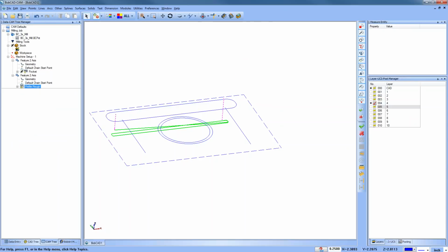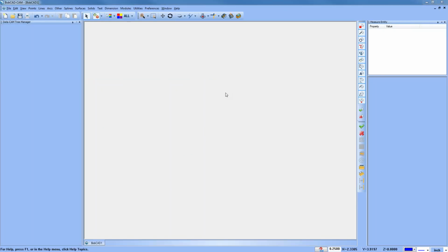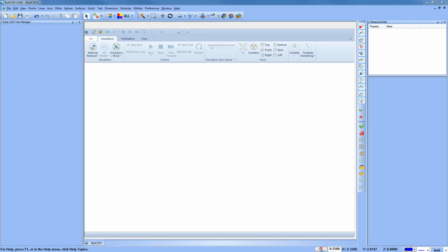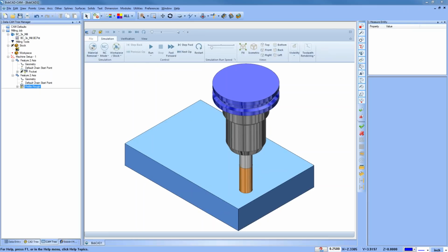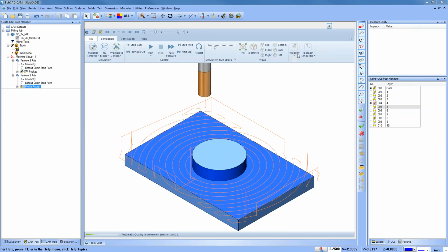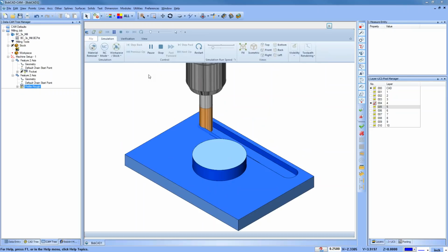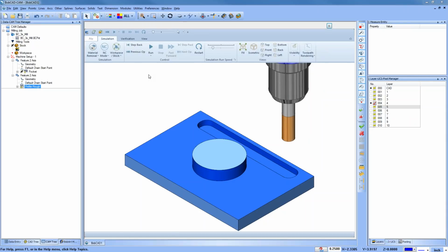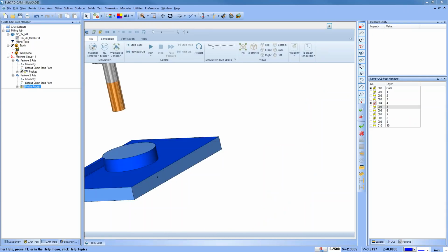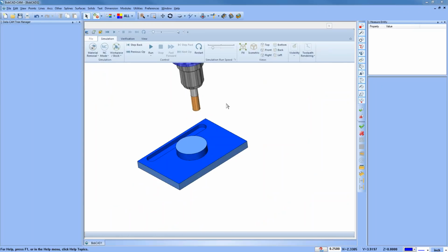Now, it's important to understand that contour ramping isn't just for slotting, though it does work well for that, and for O-ring grooves, things like that. You can also use it to rough your part out as well. That's another useful tool depending on your part geometry. Here we can see it ramp down to the bottom, and we were able to cut that slot over there. So again, you have slotting.